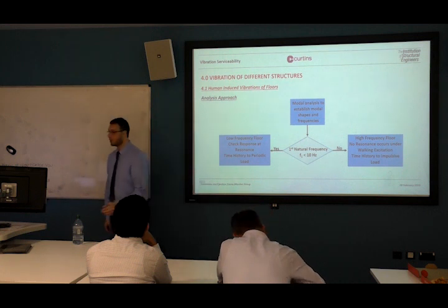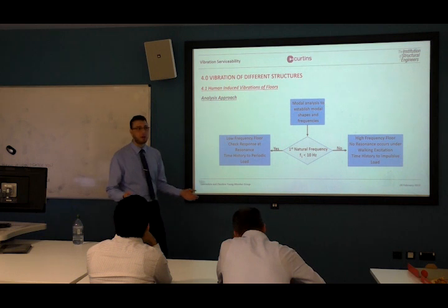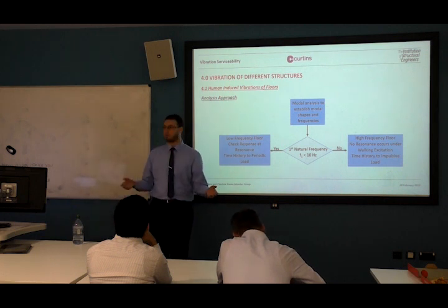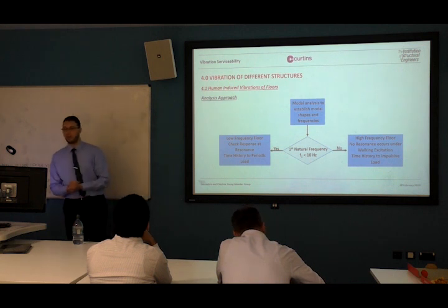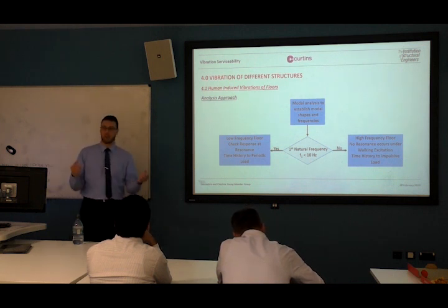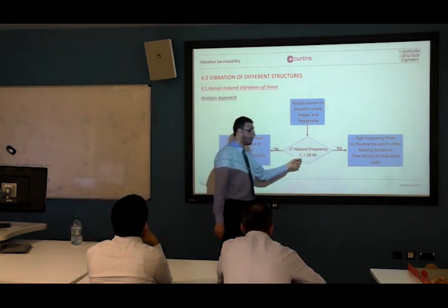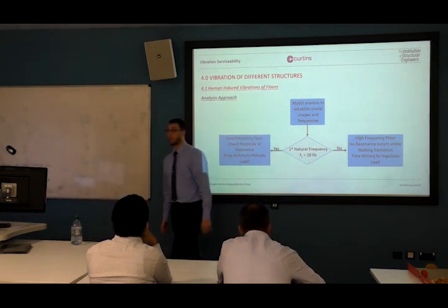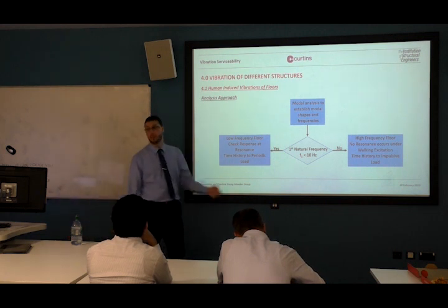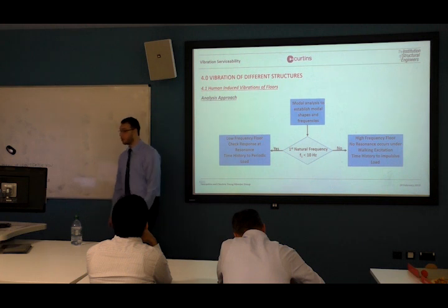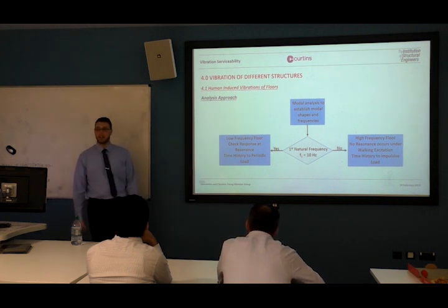Sometimes, if you design a span, let's say 2.5 meters, maybe in a corridor, and the thickness is at least 120 for fire rating or whatsoever, you might get a case where the first natural frequency is higher than 10, and this is called a high frequency floor. So usually low frequency floors are affected by resonance.